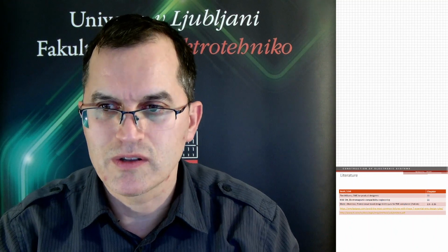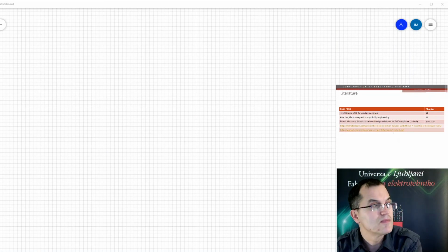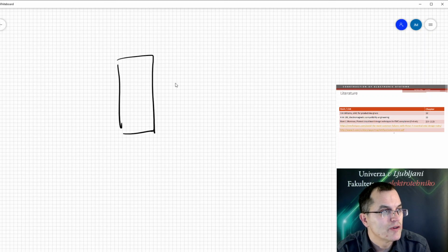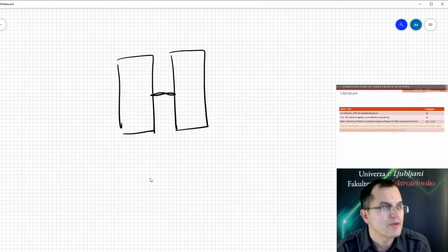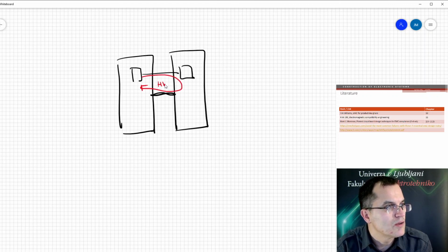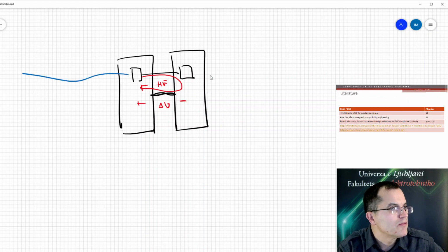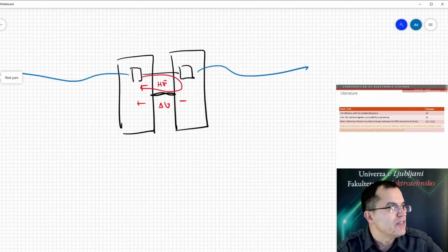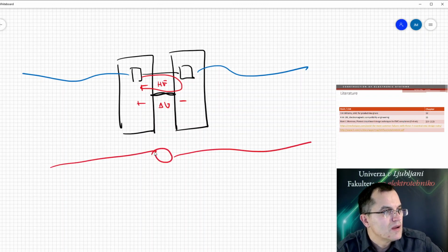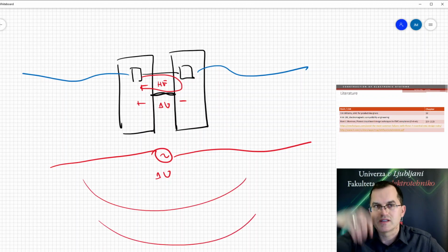Again, I talked quite a lot about that, and I'm repeating that quite a lot. So I want to be really clear, just to finish here with this. If you have two ground planes that are separated and connected in a single point, and you have a high frequency current that runs between, let's say, two components and returns here and contains high frequencies, then you would induce a high voltage difference. And then if you have one cable here, the other cable there, then you have a nice dipole generator with two cables extending as two antennas. So we have a lot of radiation that would radiate towards infinity, I would say.